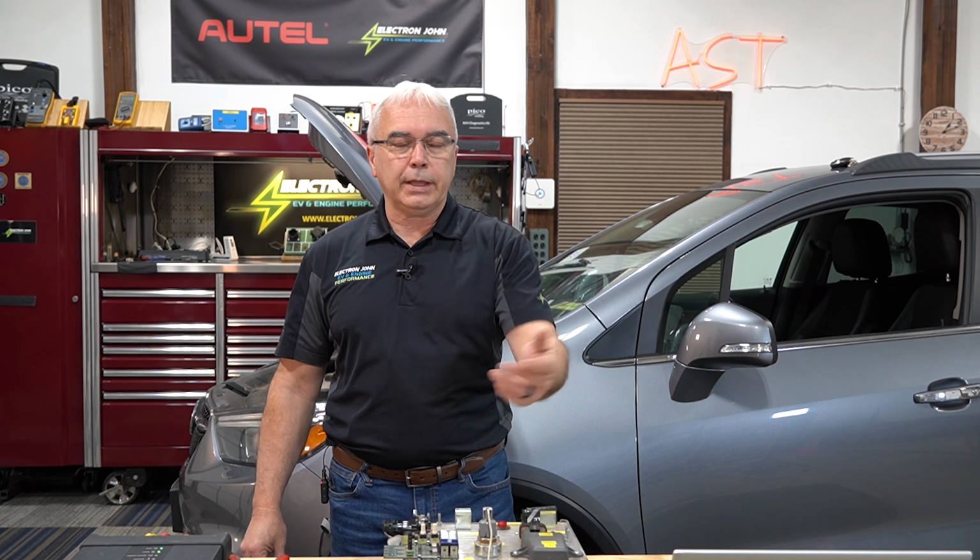Also, I can then go ahead and take a digital voltmeter and just touch the 5-volt reference with my red lead, take my black lead and touch the ground one. If I have 5 volts, I just ruled out that the ground is good as well. Plus, you know that the computer is good. So at that point, assuming there's not a vacuum leak in that one example there, it's probably going to be a bad sensor, right?